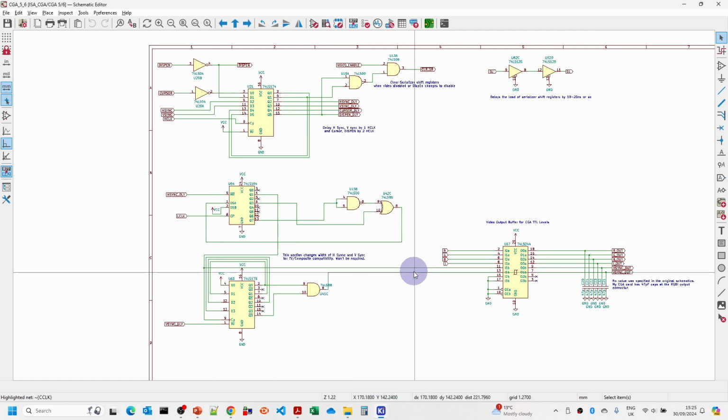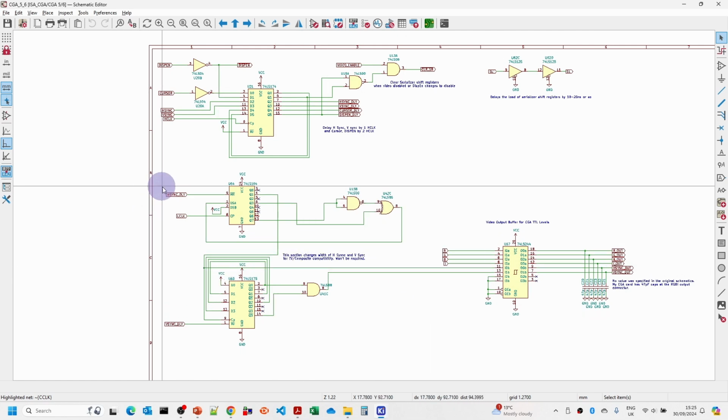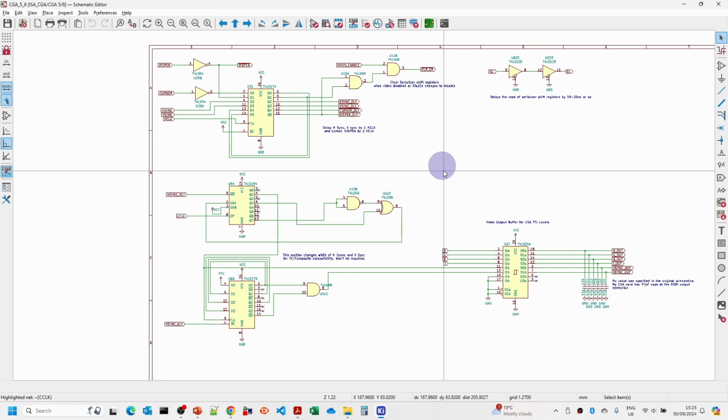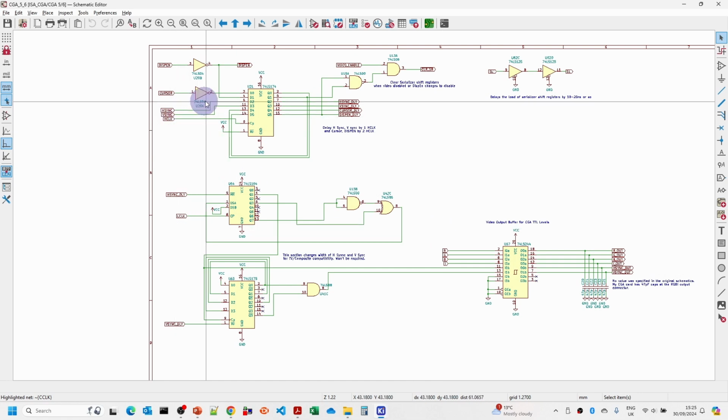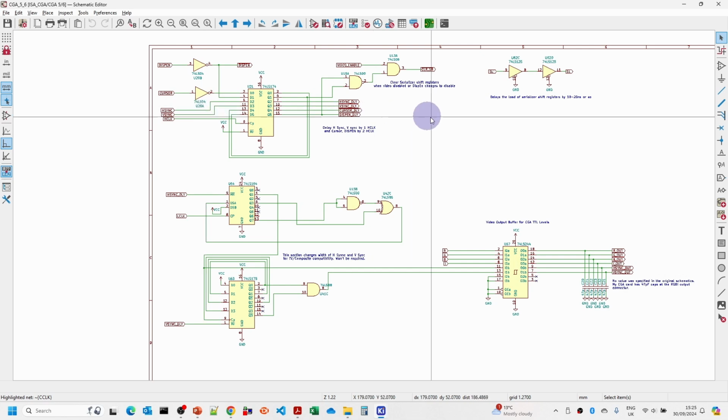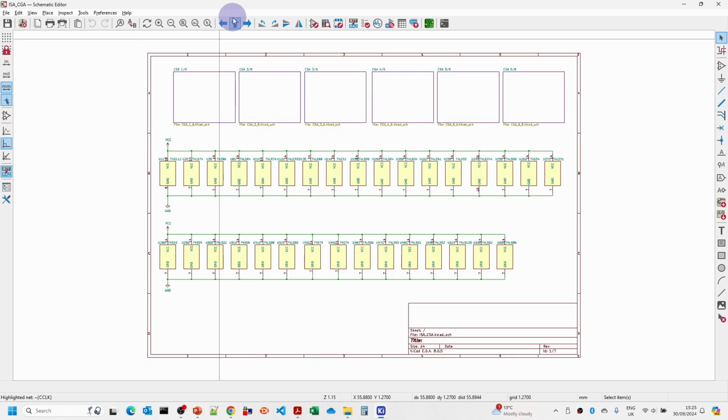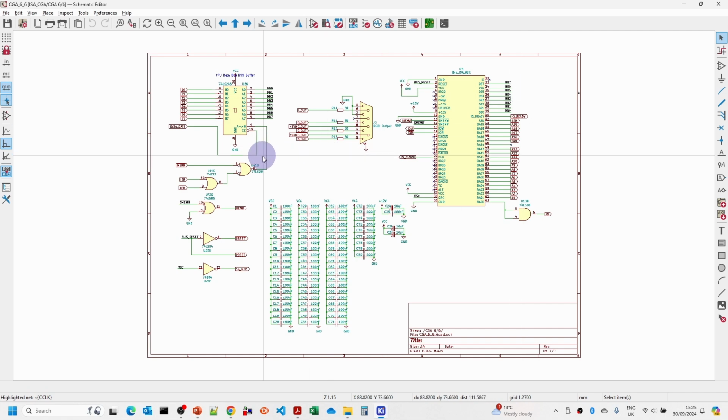And then the output, I've taken a lot of the composite color generation out of here, and in fact the H-sync and V-sync delay circuits we don't need to worry about either, so we can probably take those out. As I've said already, these flip-flops here which are used to delay some of the horizontal sync, vertical sync, cursor and display enable signals, these can be delayed by the Hitachi 6845 CRTC. Then finally I've taken out the connectors and things which are not necessary.